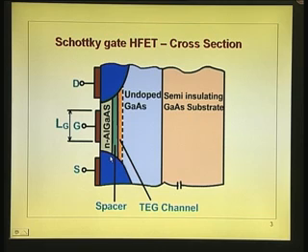We are trying to solve that problem of heavy doping here. If the entire layer is depleted, and the charge present here is controlled by means of gate voltage, you have the current through this entire shaded region, the yellow color here, that is the 2-dimensional electron gas. That is actually controlled by the gate voltage, exactly the same way as the MOSFET.